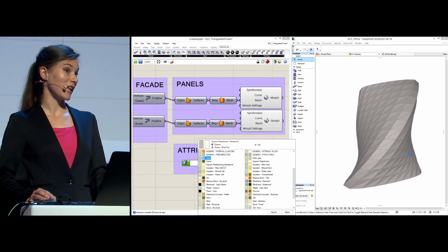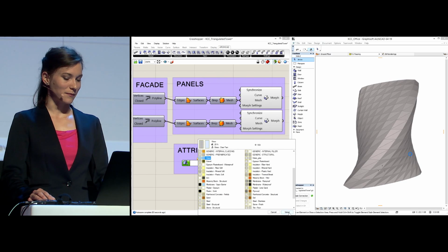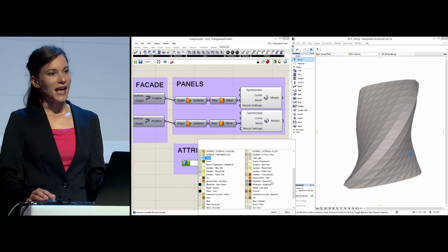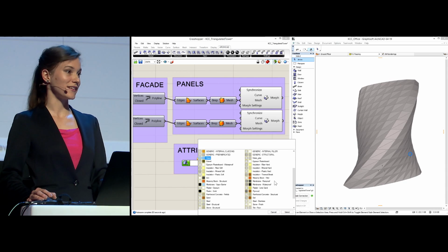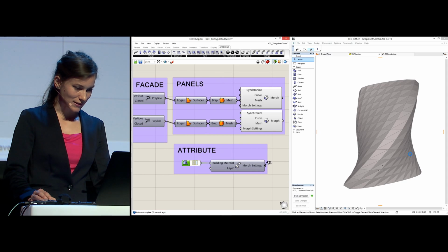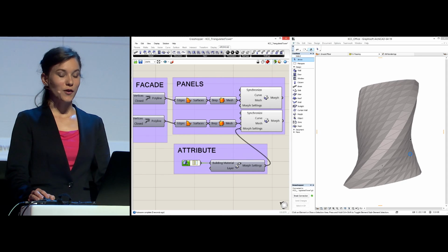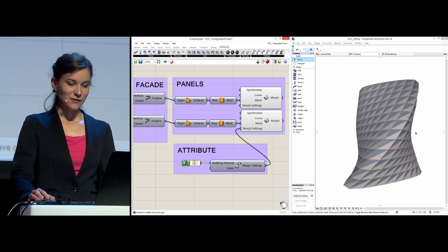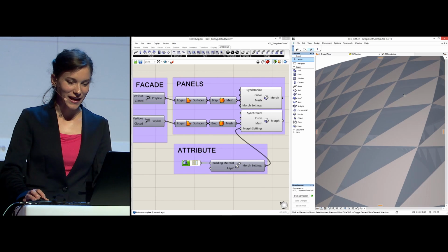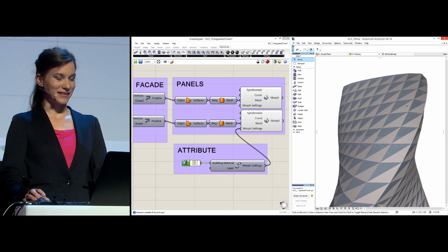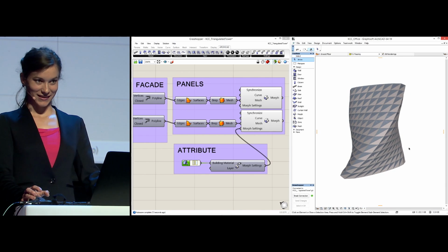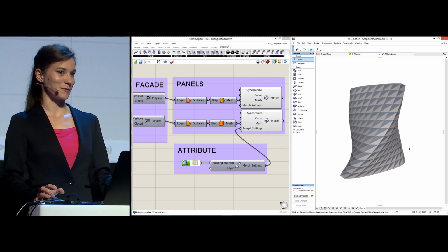And let's say it should be glass, because we want to have transparent panels. And remember, now we are in the Grasshopper window, and still we have access to project-specific ARCHICAD data. So let's select glass and connect it to the rest of the code. Of course, ARCHICAD will do the changes for us within a blink of an eye. Every second panel is transparent now, just like we wanted. Well, I hope you agree that the model now starts to look like a building.